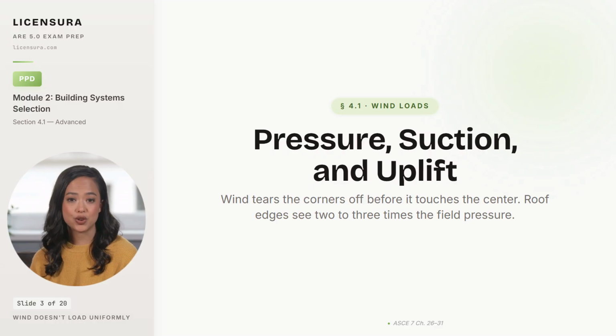Here's the uncomfortable truth about wind. It doesn't load a building uniformly. Architects think of wind as a single horizontal push, but ASCE 7 treats it as 5 distinct loadings on 5 distinct surfaces, plus an internal pressure that depends on whether your envelope holds tight or breaches. Roof corners experience 2 to 3 times the pressure of the roof field, which is why every post-hurricane forensic report you'll ever read starts at the corner of the roof and works inward.